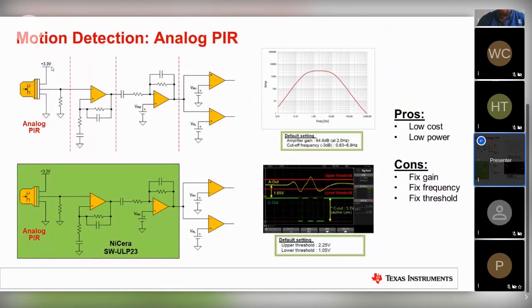the design that is normally used today, and that is going to be a PIR sensor connected normally to a double gain stage, where we have a bandpass filter. The bandpass filter will cut the DC component out, will amplify the AC component, and normally we'll have a bandpass between, let's say, 0.4 and maybe 10 hertz. Now, it depends on your application, depends on the market that you're targeting, that can be adjusted.